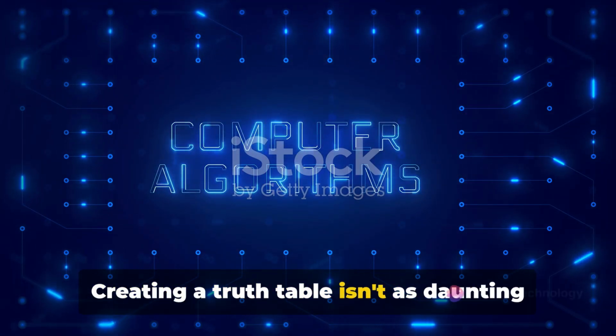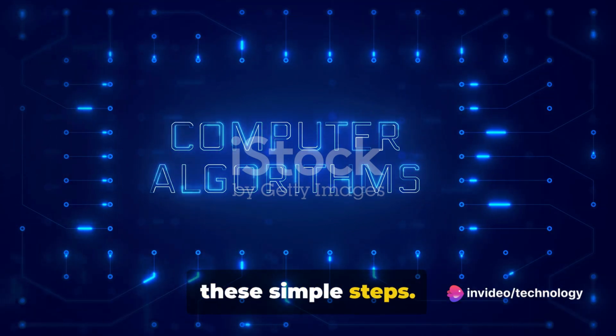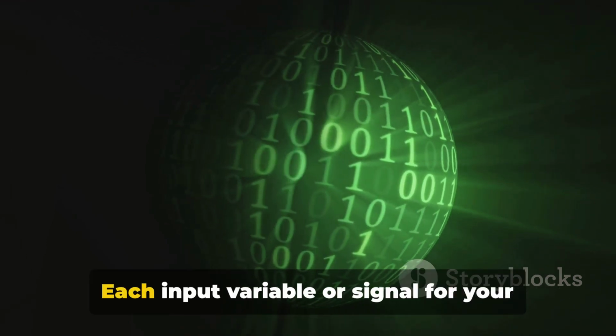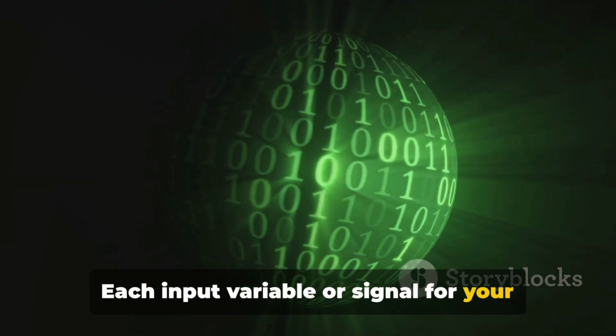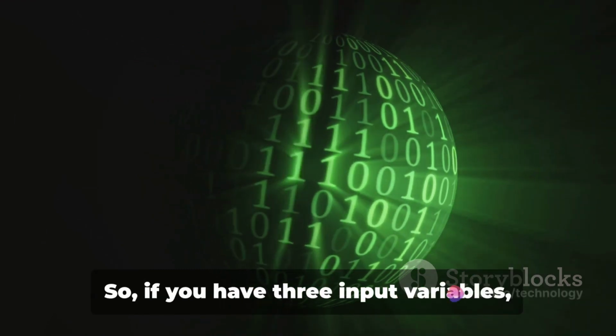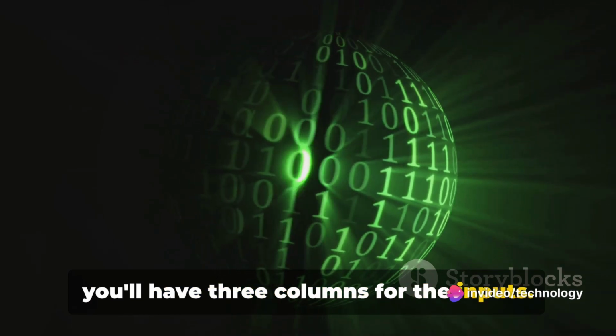Creating a truth table isn't as daunting as it may seem, especially if you follow these simple steps. First off, we need to identify the number of inputs. Each input variable or signal for your Boolean function will be represented by a column in your truth table. So if you have 3 input variables, you'll have 3 columns for the inputs.